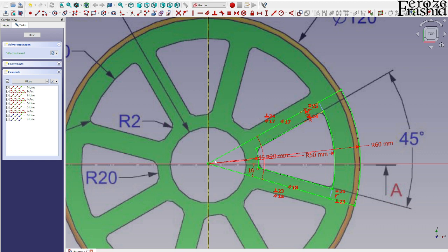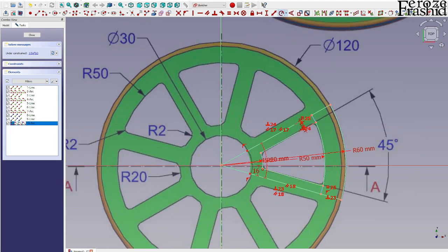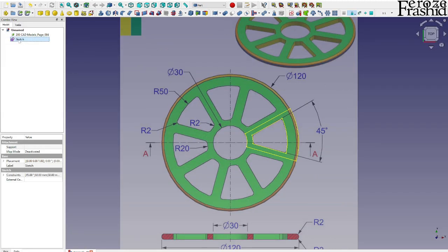Okay, we'll have to make this a cut, so we can do that now real quick. Actually, what I can do is I can make this curve, right? And this is radius 15, and to trim this off, yeah, I would rather, I don't want to trim it right now. I just want to make the construction and draw these two solid lines, so that way I am not losing any constraints.